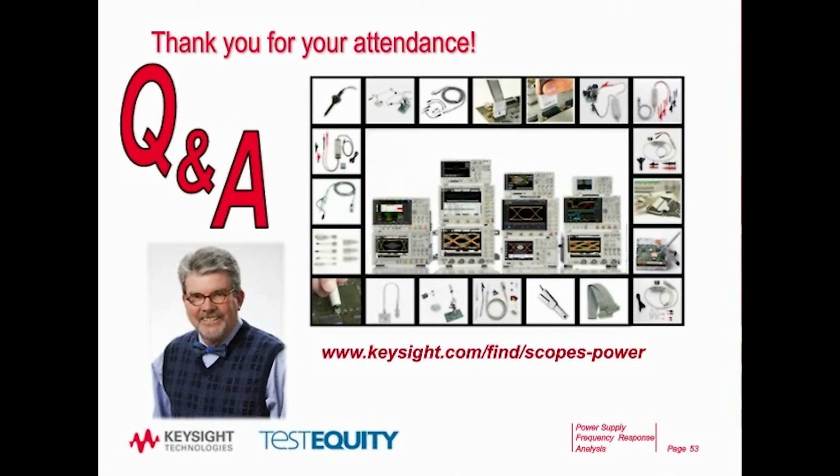Now, I think I saw another related question, probe capacitance. The passive probe is certainly going to have more capacitance than the active probe. However, typically when you're probing the output of a power supply, it's got a lot of capacitance on it anyway. So that's not going to really affect your measurements that much.